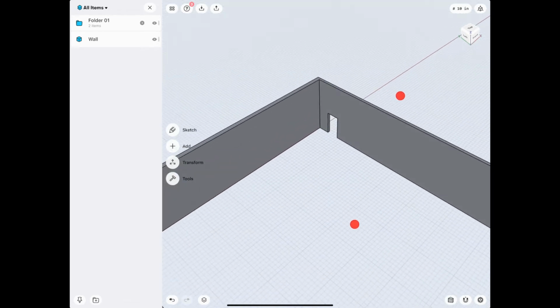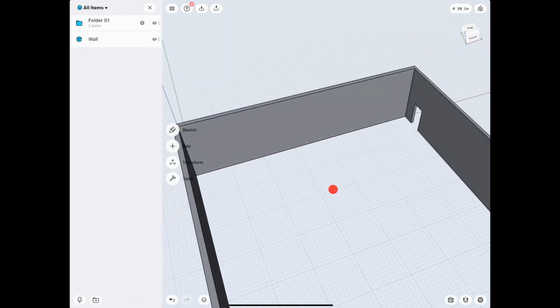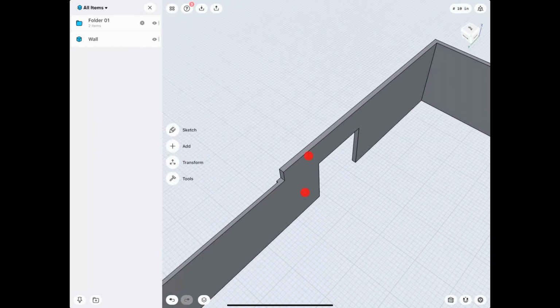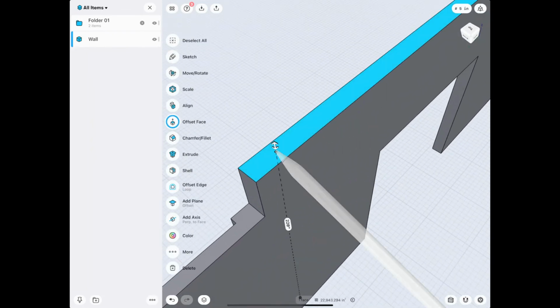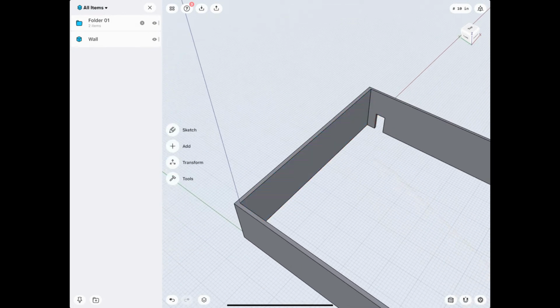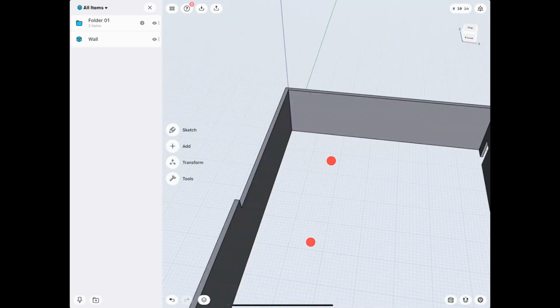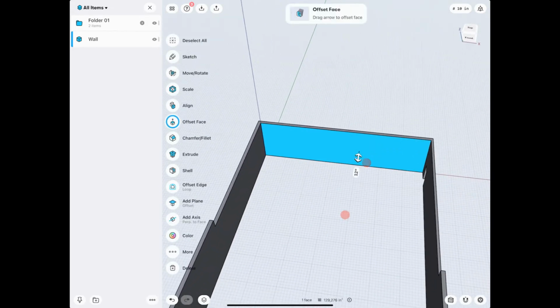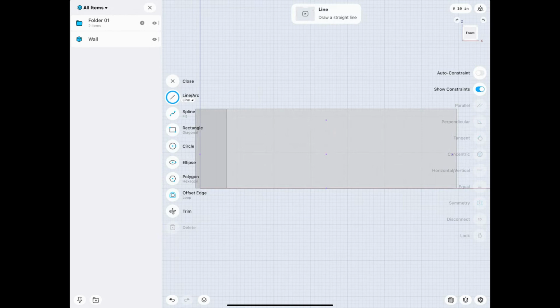To make a window, it's pretty much the same process we used to draw on the face before. We can draw on a face there. So with the pencil, tap somewhere else so nothing is selected. And then with a finger, double tap. And oh, I see everything like this in front of me. That's not good. Not a big deal.